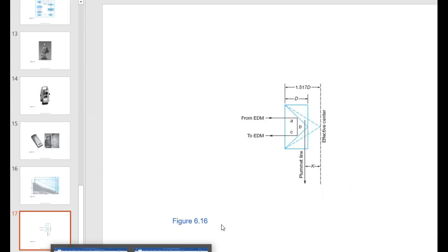So when you have a total station on a prism, you have to make sure that the total station is set up so that the K value is the same as the K value for the prism. Generally speaking, the prisms are stamped or have stickers on them that tell you what the constant is, or you can look up the manufacturer and see what the constant would be, and then you can use that value in order to get ultra precise distances between the prism and the total station.